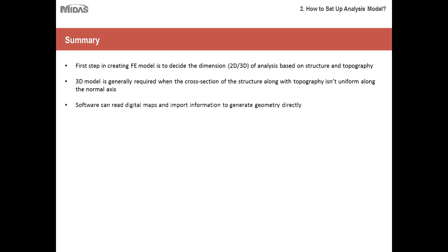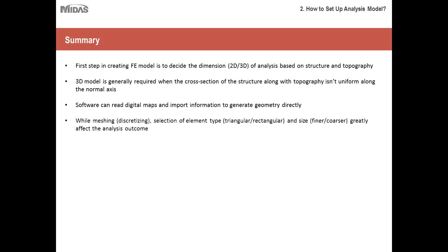Then the software can read digital map and import information to generate geometry directly. So there are good software out there which can directly read complex geometry data from your digital maps and create geometry. And then while meshing or discretization, selection of element size, whether to use triangular or rectangular elements, and the size, whether to go for finer or coarser mesh, it greatly affects the analysis outcome.